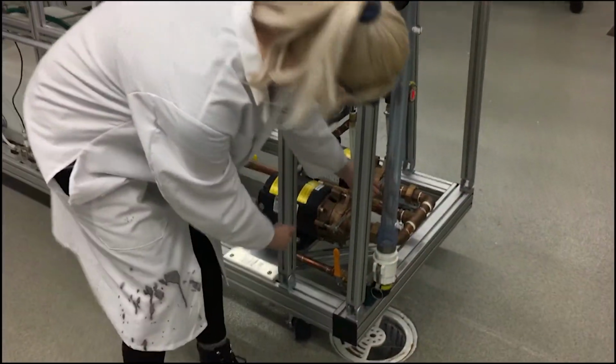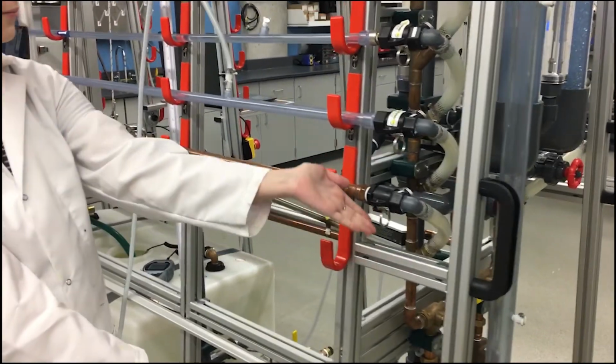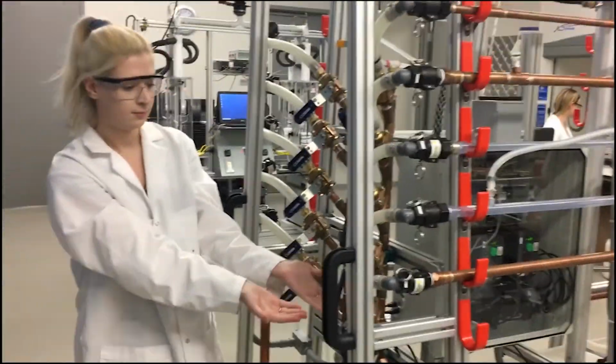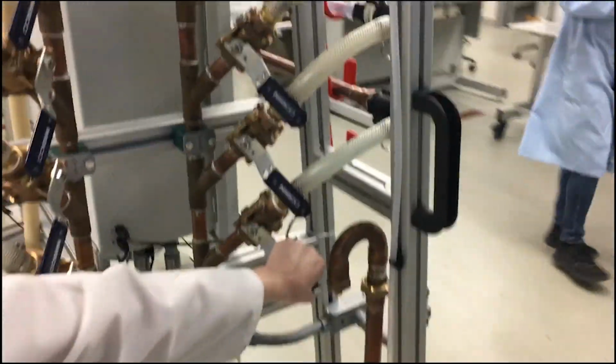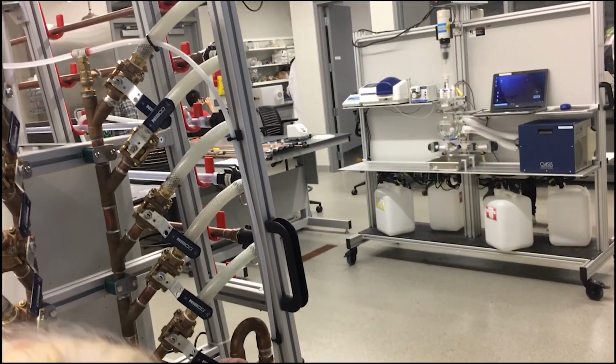The design problem consists of 2 parts. The first is to find the total pressure drop from the outlet of the pump to the inlet of the pump across the system. The second part is to solve the power consumption of the pump. To solve for the pressure drop, information about the system must be compiled. First, we drew the system, taking note of different valve types and fittings within the system.